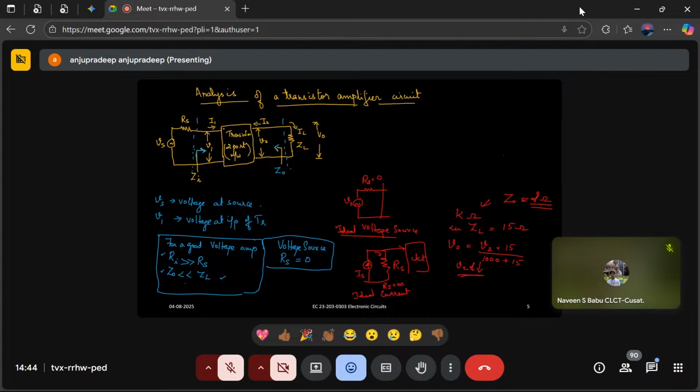So what do we have? You have a transistor which is considered as a two-port network. That is what we have seen earlier. That two-port network has a V1 applied to it, and I1 will flow through it. The output of that two-port network is V2, and current I2 is flowing into the transistor, the same as earlier. So what you have between these two blue lines is the equivalent circuit of the transistor.